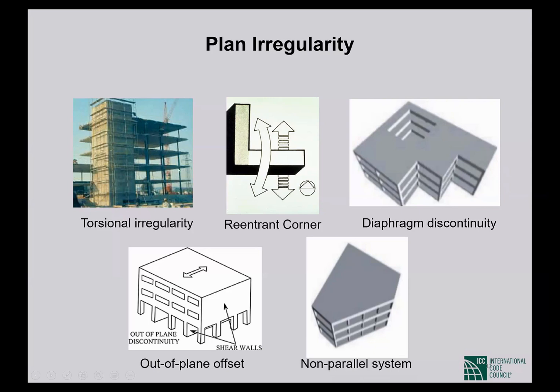So what will happen during an earthquake is that this stiff core will be pinned at this place, and the columns at the floor will be twisted, will be rotated, making this stiff core the center of rotation. So there will be twisting on the columns of the building.